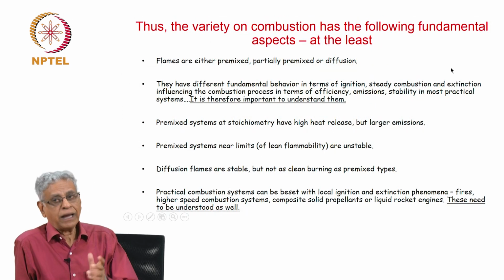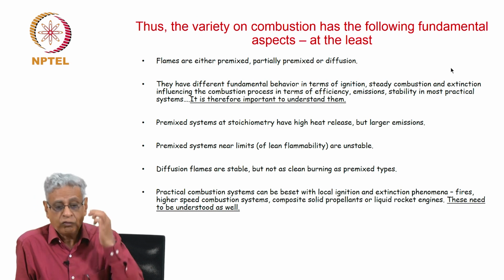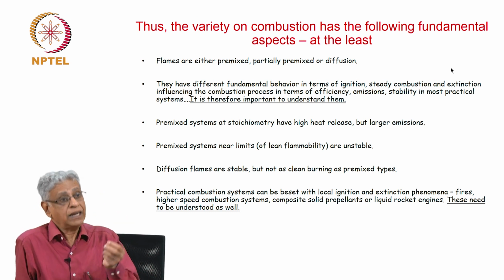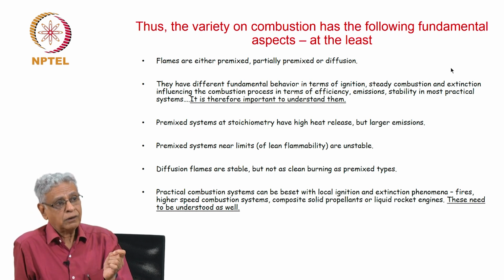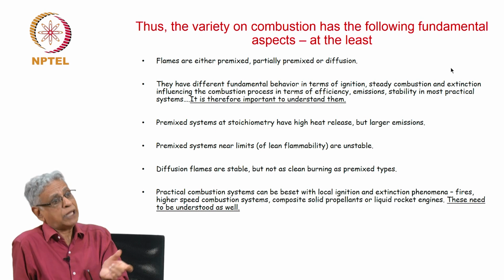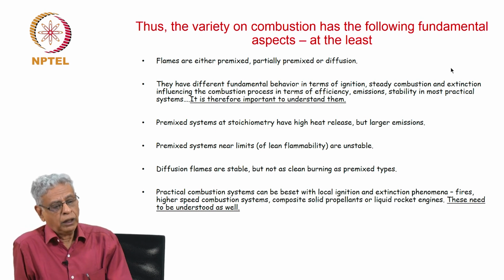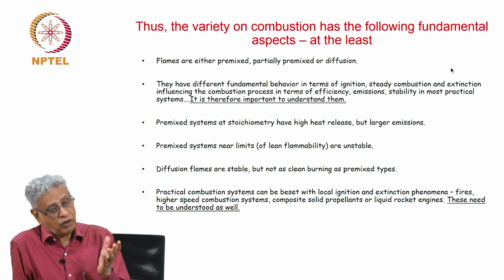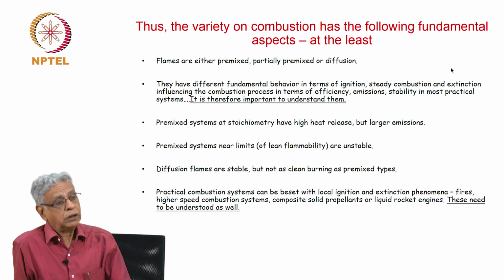Okay, I want to summarize now. There is a variety of combustion processes following fundamental aspects at the least. Flames are either premixed, I did not mention partially premixed, they could be partially premixed, or diffusion. They have different fundamental behavior in terms of ignition, steady combustion and extinction.